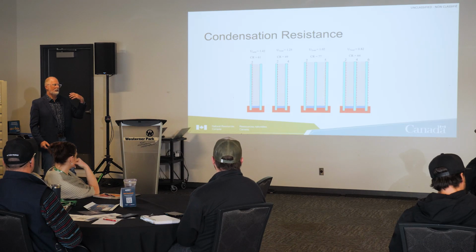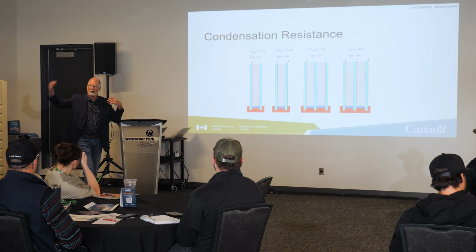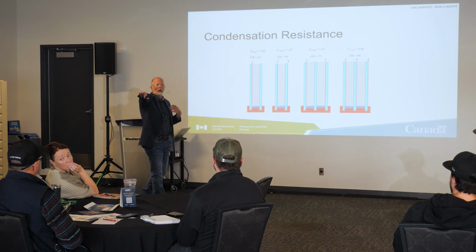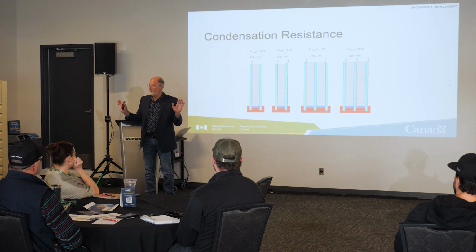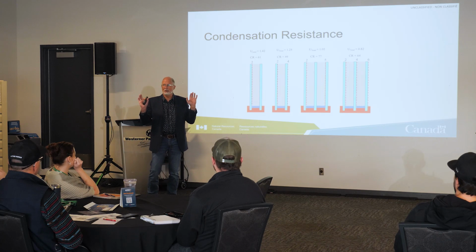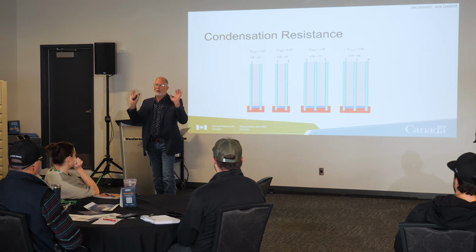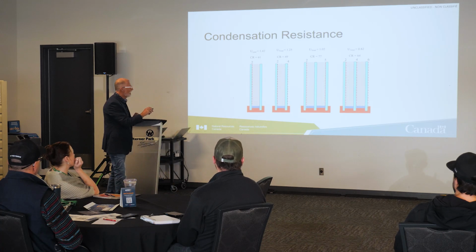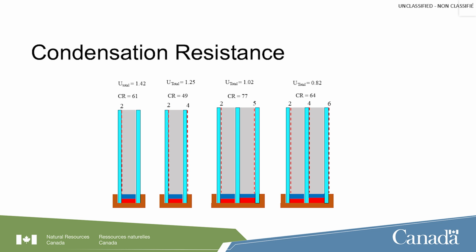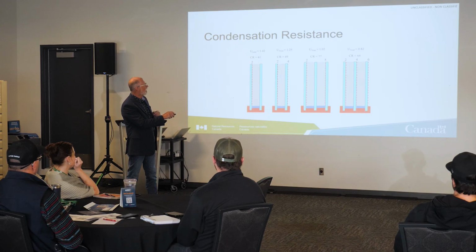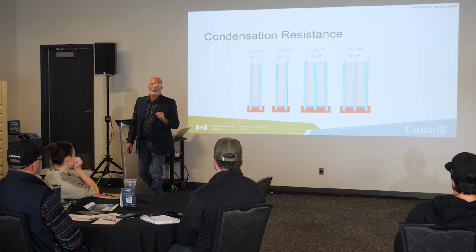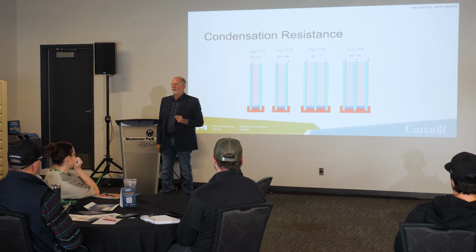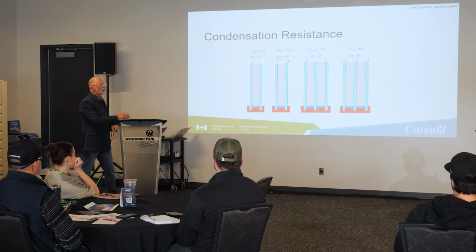So how do I offset that? Let's bring in the other parts of the building. So there's my window right there. I have a homeowner that likes reasonably high humidity. I've established that during the sales process. They like high humidity. I don't want to have condensation on my window. So you probably want this window, but then you look at this and you go, well, that's not going to perform very good on a net zero house, so I want this window. How do I offset this on that glass? Air movement. All I need is a big fan there pushing air at the window, and my condensation issue goes away. If I don't want to move air, then I worry about the condensation resistance.